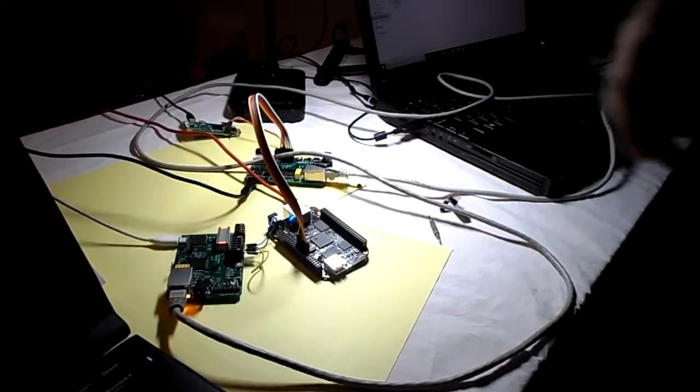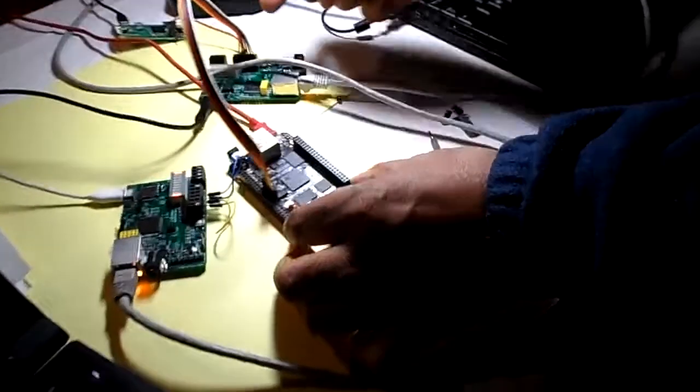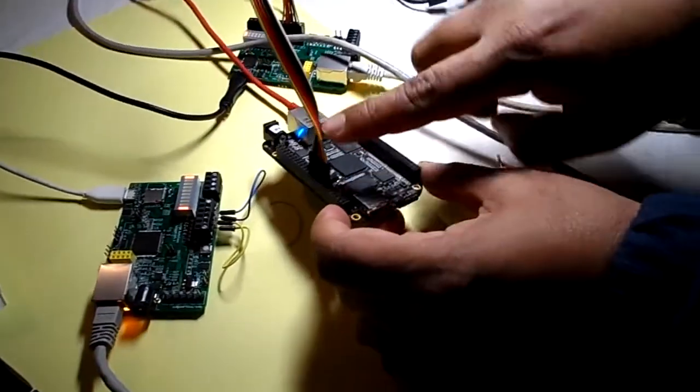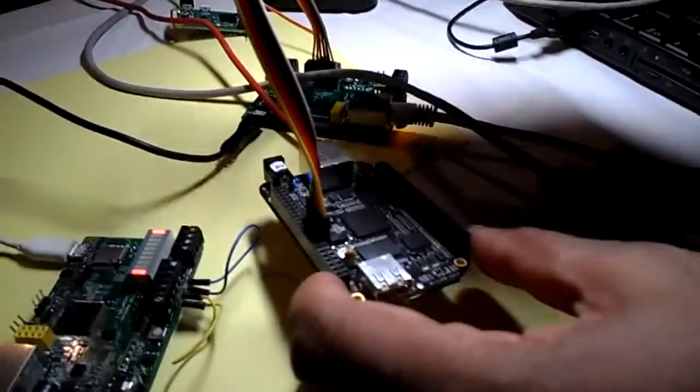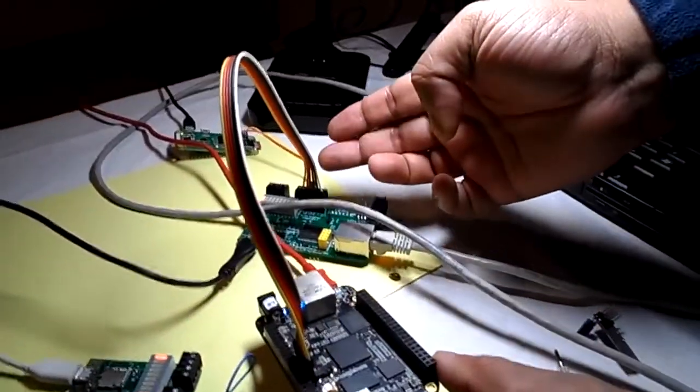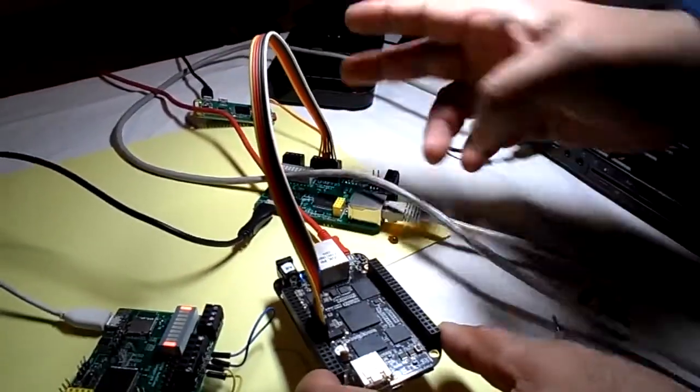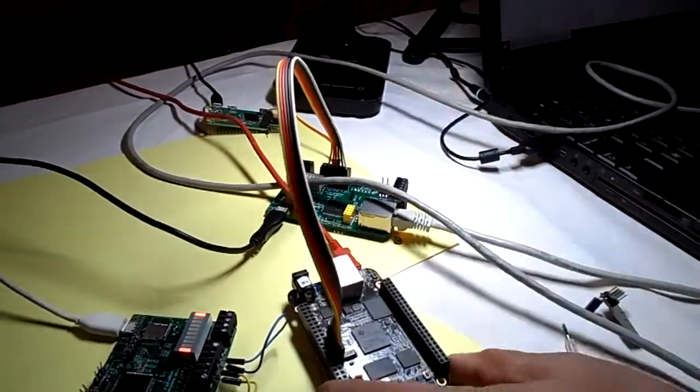So right now I have 2 Ethernet bridge boards and 1 BeagleBone Black. The BeagleBone Black serial terminal and Ethernet bridge are connected with a 6-pin ribbon cable, and BeagleBone Black is just powered on. Each Ethernet bridge has 2 TTL and 1 RS-485 UART port. So the setup is on Windows, where we're going to start the Ethernet terminal.